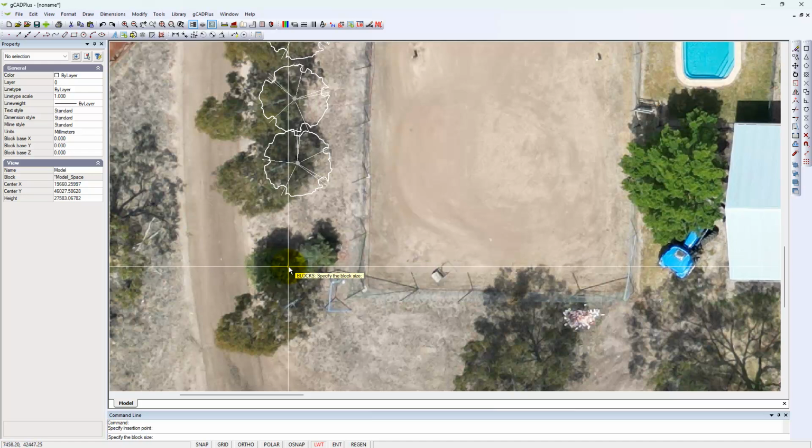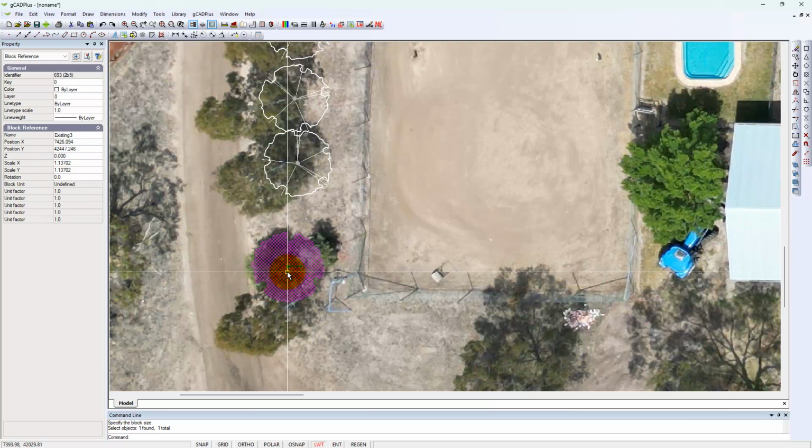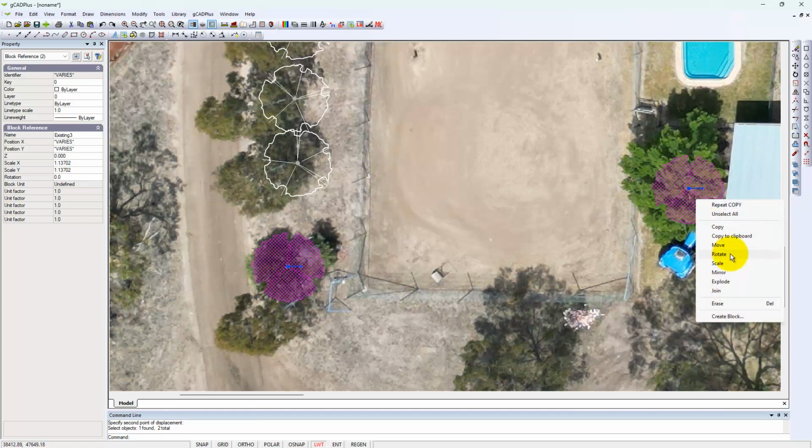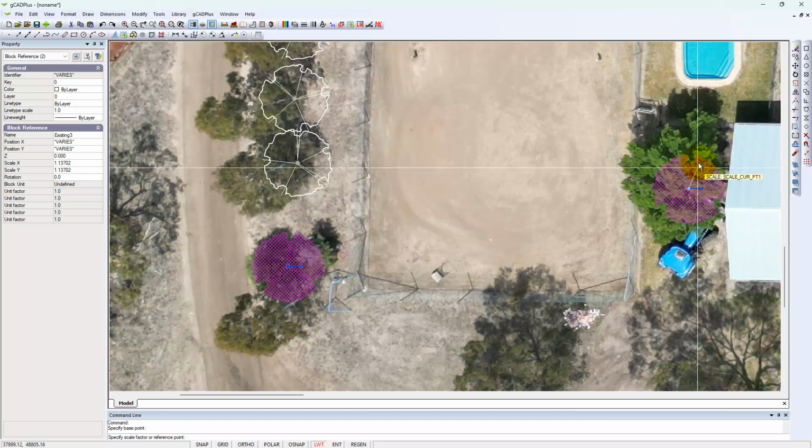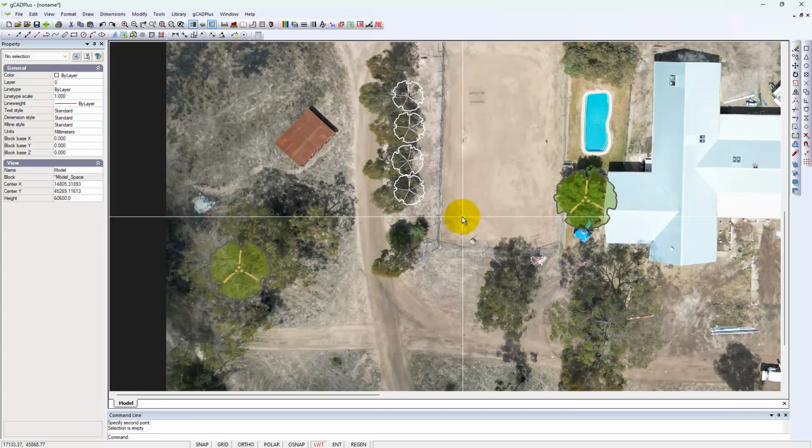I guess what's happened here is that these are bushes. This one's a bush, so it doesn't cast such a long shade. And this one's effectively a bush as well. So we can copy that one, pop it over there, and pop it down, pick it again, right click and scale it, come out to there, and that's a fair guess as to its canopy diameter.